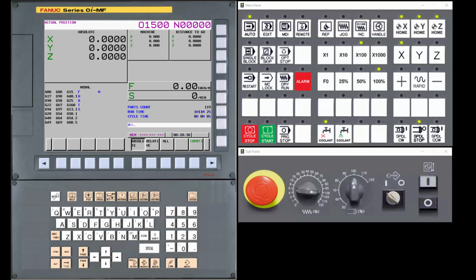It is recommended that you format the memory card or USB memory stick on the CNC before performing the backup. Make sure that any files already stored on the backup device are already saved somewhere else or are no longer needed. Note that the memory technology used in compact flash cards and USB memory sticks is not suitable for a long-term backup. All the files must be transferred to a PC or network drive, preferably one that is also routinely backed up by another secure system off-site or in the cloud.